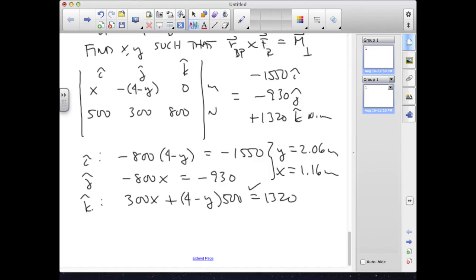I realize this was a long exercise, but the point is that the equivalent force system in 3 dimensions is probably best calculated using the vector approach for the shift, and that it doesn't matter what you pick for your initial reference point. As long as you're consistent in doing the calculations, you should find that the location of that resultant force parallel moment pair ends up at the same location.